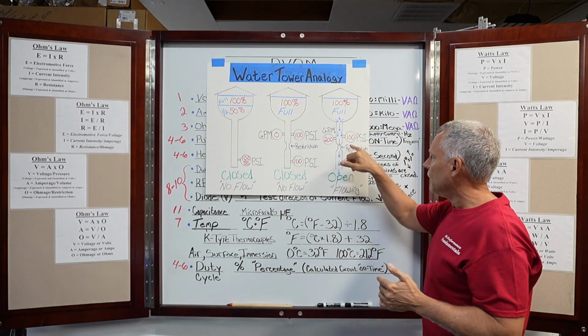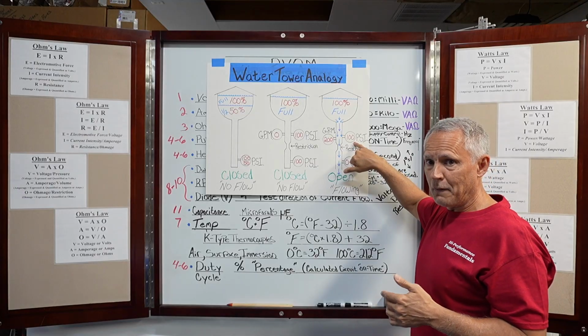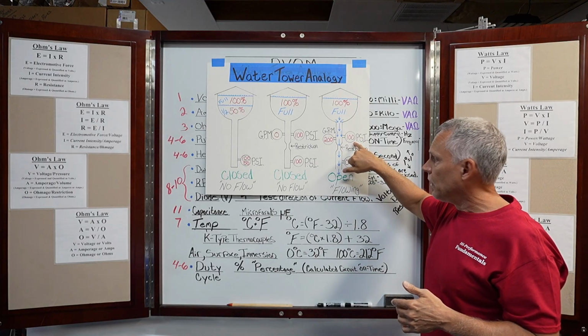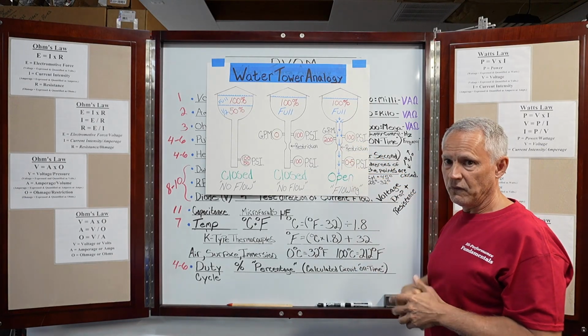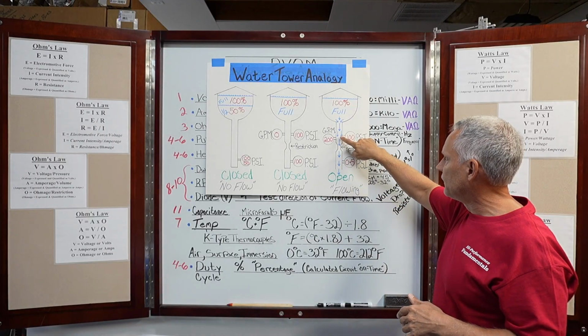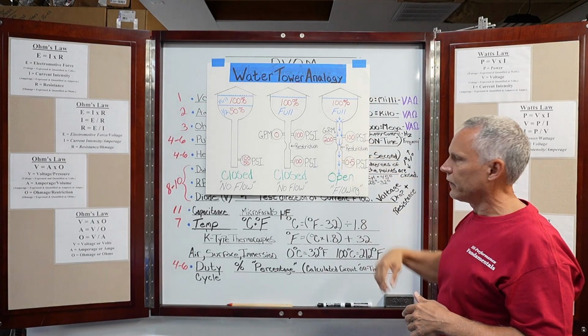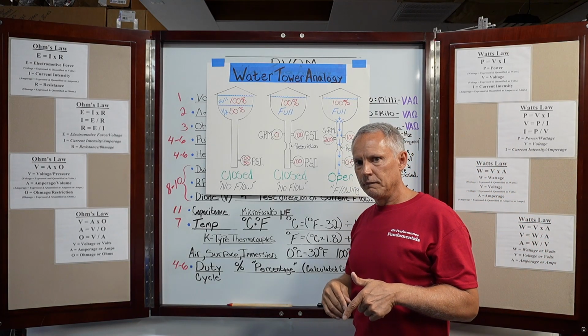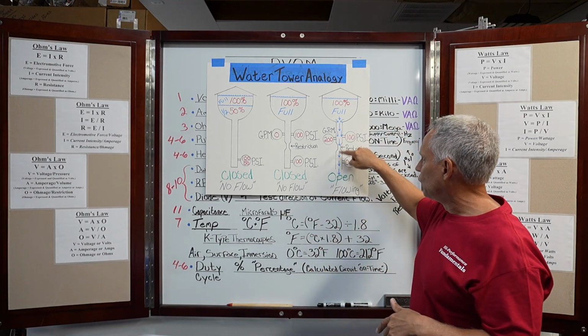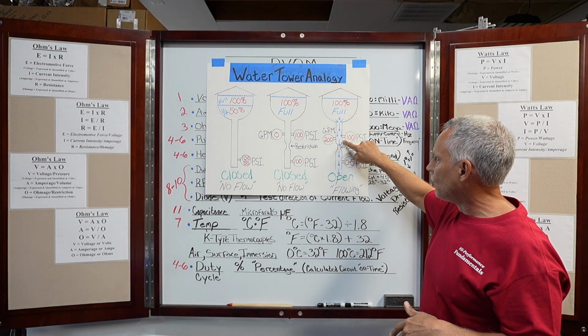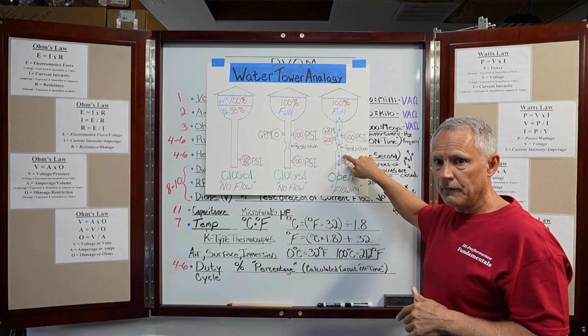So in this case, instead of that being a pressure gauge, that's going to be a voltmeter. Instead of that being a pressure gauge, that's also going to be the voltmeter, right? So we're going to measure the resistance across that circuit by voltage drop, okay? So since there's a restriction in flow, we'll have greater voltage here than we have here, okay?